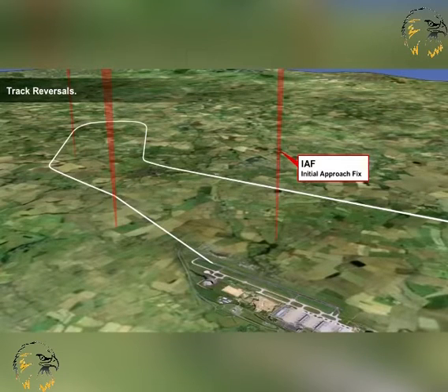A simple procedure should provide for an outbound track from the fixed facility, followed by a track reversal inbound back towards the runway. This is called a procedure turn or base turn. The standard procedure for track reversal is the procedure turn, and is defined as a turn from outbound to inbound in which flown tracks are reciprocals. It has two variations, which we will show you.